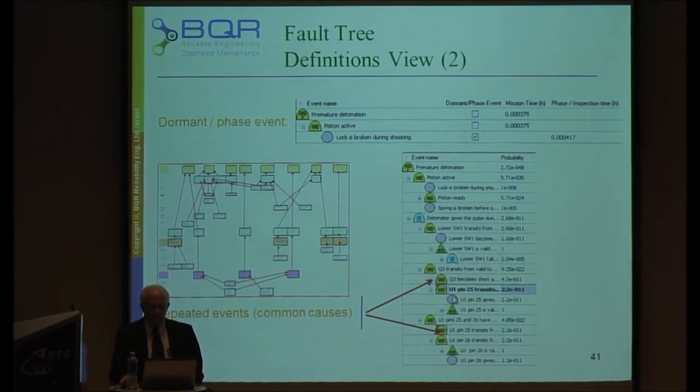So we call it common cause. This sometimes makes it easier to analyze because you can see how the common cause affects the two effects. If you don't use the common cause technique, you need to build up two components, and you need to combine that those two components will fail at the same time. So it's difficult. So common cause is the way you build up the model.